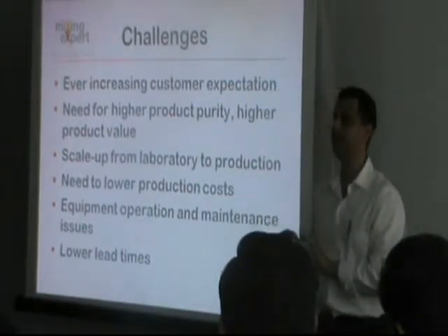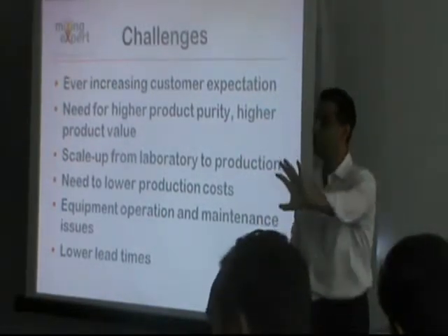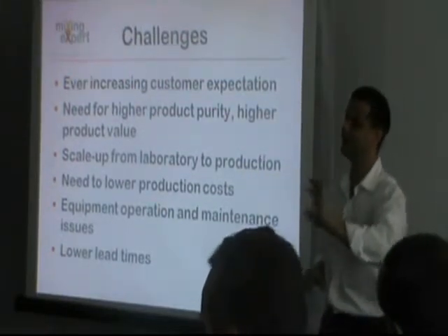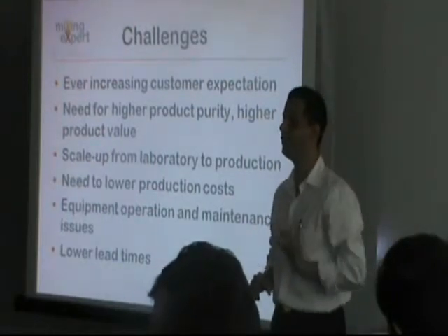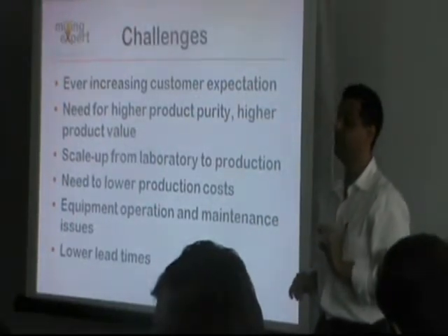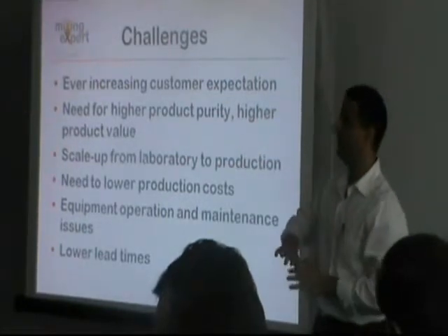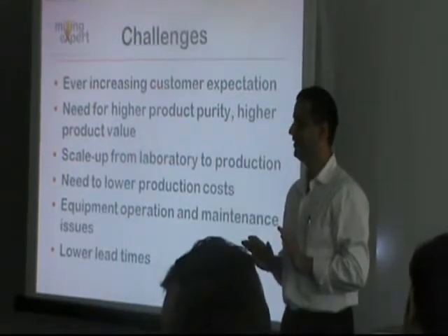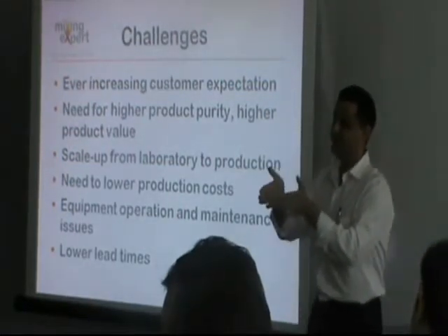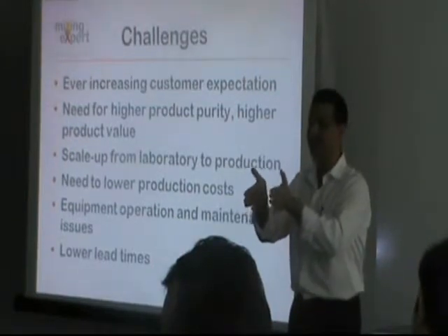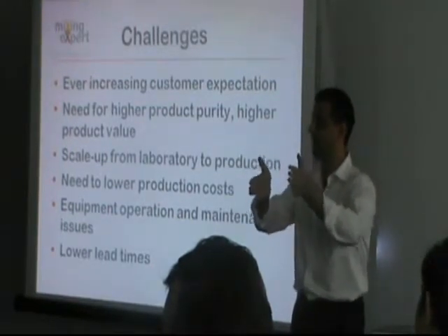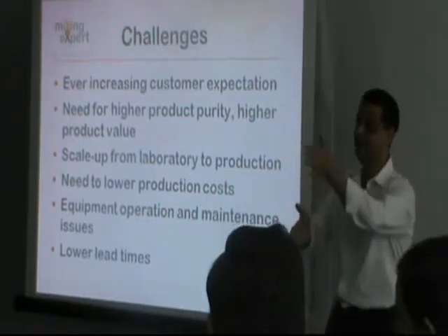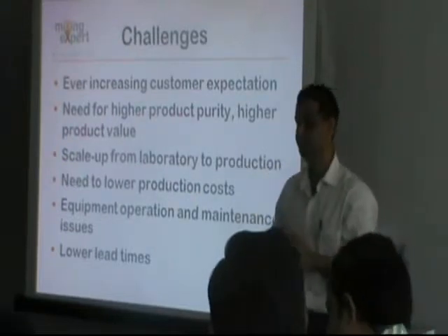The other important thing is that any motor, say for example a 5 horsepower motor, has a maximum rated current of I think 7.2 amperes, somewhere around that range. Now the motor, even if we are running at no load condition, will draw some amperage, right? So in the real sense, the power drawn in the mixing is the difference between the current drawn at the loaded condition less the current drawn when it is running idle.